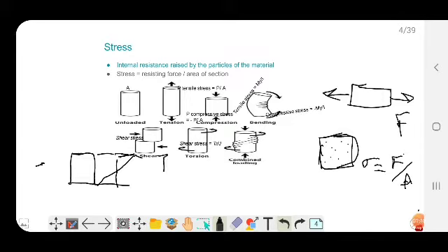So this is tension, this is compression, and we'll be considering the body to be made up of fibers like this, and somewhere here a fiber will be experiencing net stress of 0, and that axis is the neutral axis.